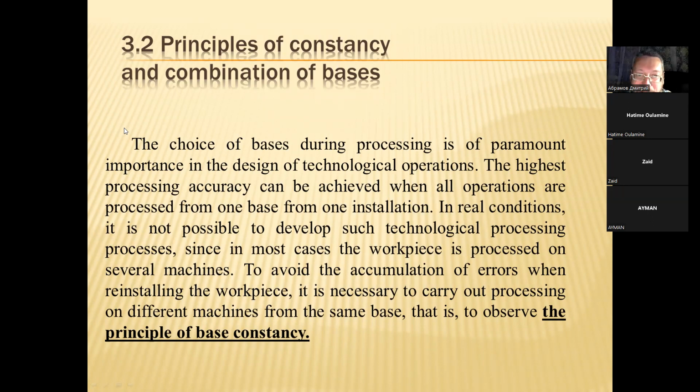The choice of bases during processing is of paramount importance in the design of technological operations. The highest processing accuracy can be achieved when all operations are processed from one base, from one installation.